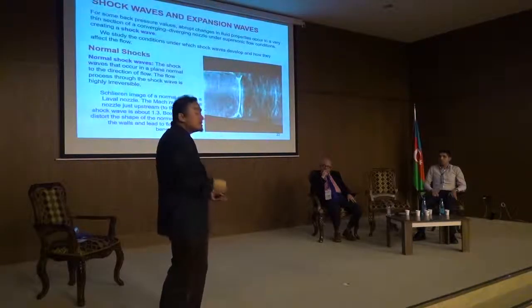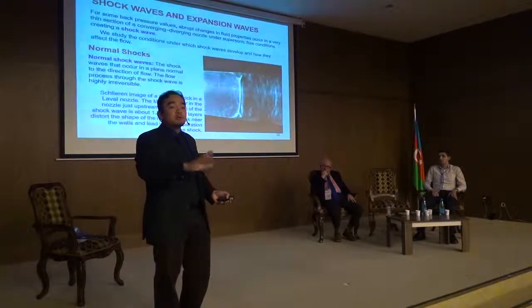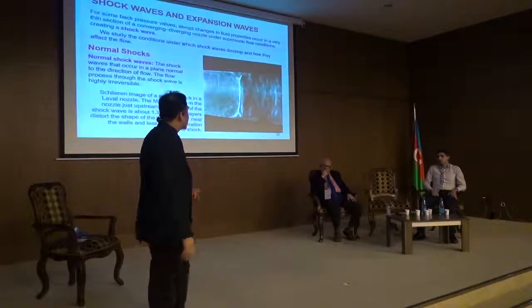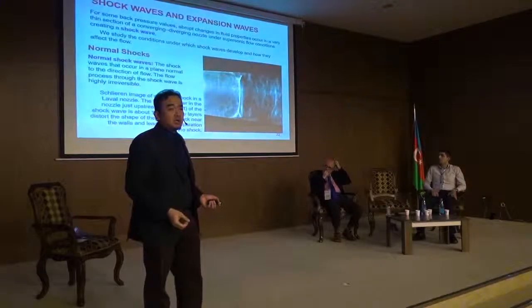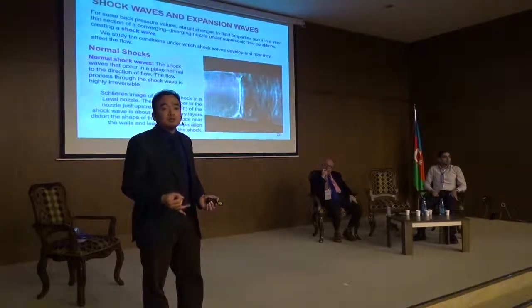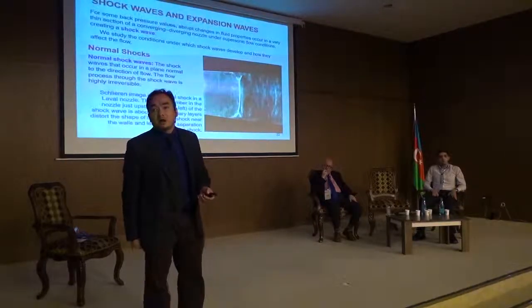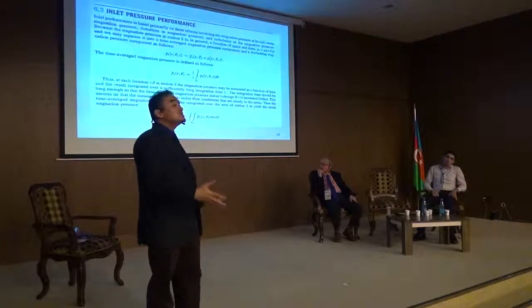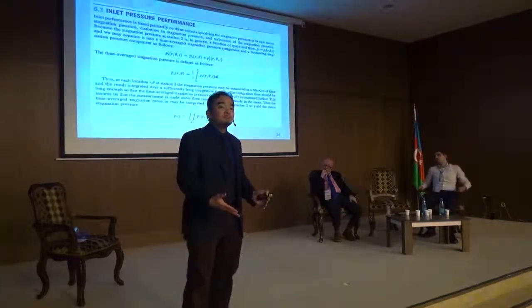It's a very tiny layer, but the difference in the properties is significant, downstream and upstream of the shock waves. The pressure, the densities, the temperatures increase very highly, okay? So this would affect, for example, the performance of the compressor.